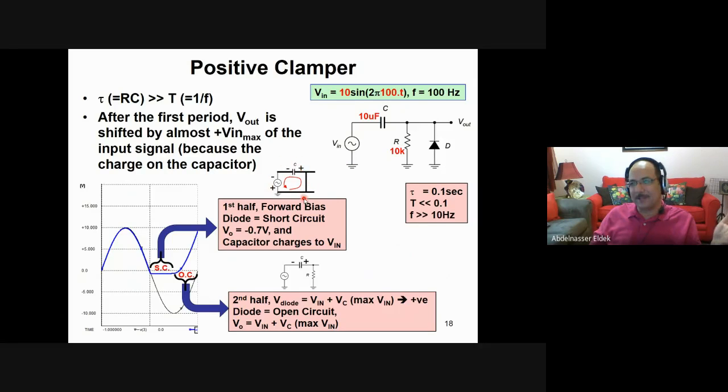Imagine that you have this circuit. Of course, here the time constant is what? C times what? The resistance is 0. You don't have any resistance because you shorted the resistor already. So the resistance is 0. Then the time constant is supposed to be theoretically 0. So this means that the capacitor will charge in no time or a very, very small time.